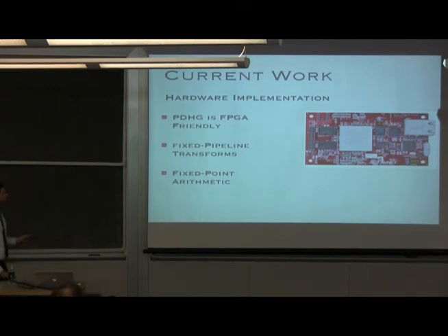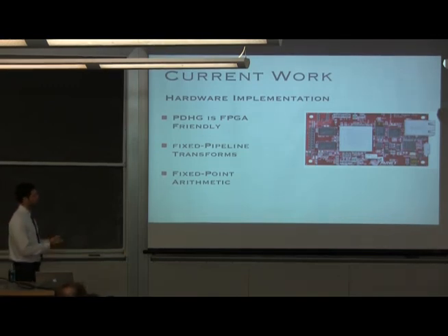And finally, we can only do fixed point arithmetic effectively on the FPGA. We can't do any floating point arithmetic. And as a result, you have to rescale the algorithms appropriately. You have to choose your time steps in a very clever way. But provided that you scale the problem appropriately, it's possible to make this work in fixed point arithmetic. We've built a real-time FPGA implementation that works for simple frame-by-frame reconstruction. And the problem we're working on now is building a new FPGA implementation that will actually do these compressive video reconstructions that can get up to higher resolutions.